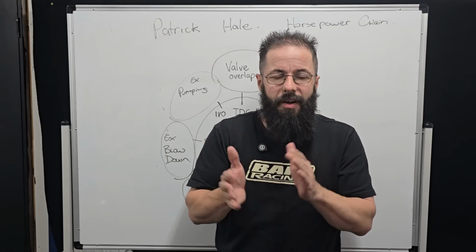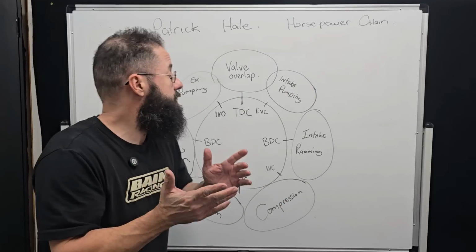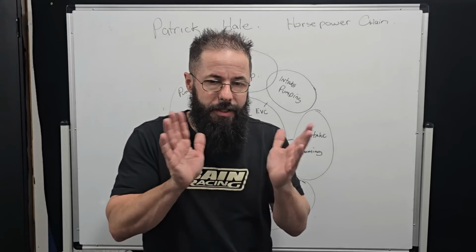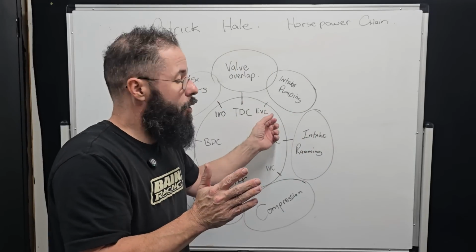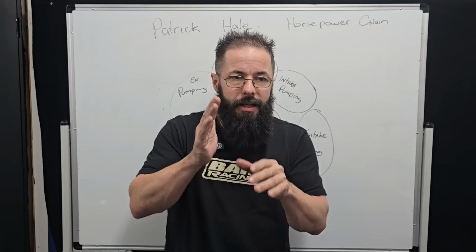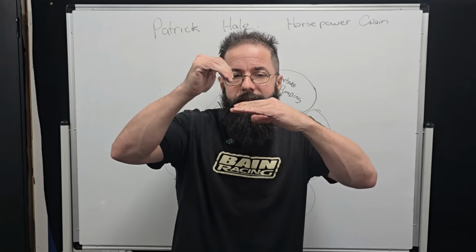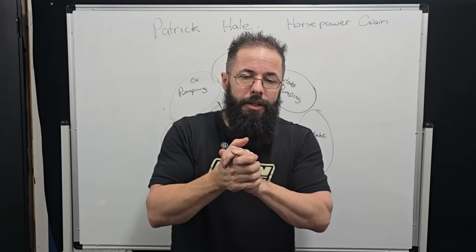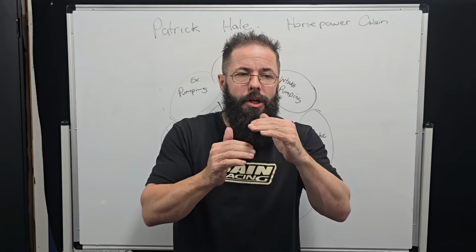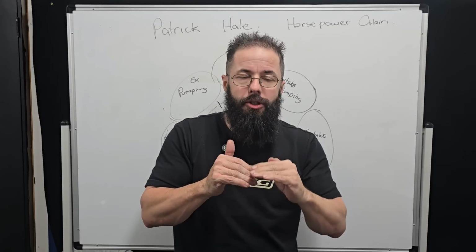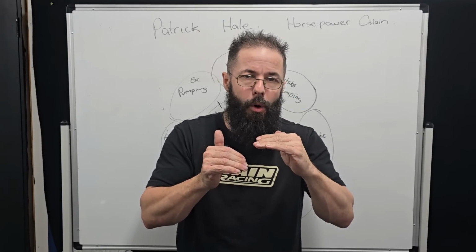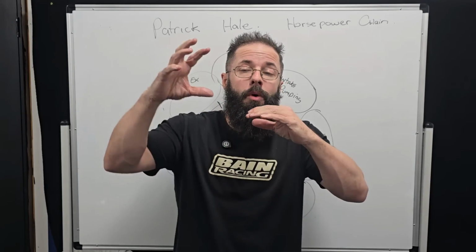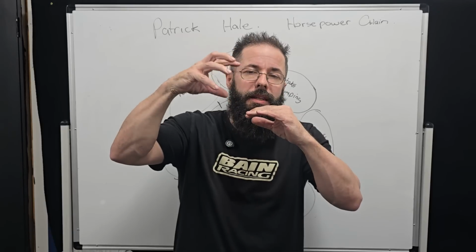Again, we'll break it up into different areas. Our most important part, I would say, would come down to our intake opening event. And again, this is going to be based off our exhaust closing event because that's going to set our LSA. But remember, we're opening the valve as the piston's coming up to TDC. And this is why wave tuning is so important, because we have no inertia, we have no piston drawing mechanism. So the piston hasn't gone down the bore at all yet to create the negative pressure needed for the atmosphere to fill it. So we're relying on a high pressure wave landing at the back of the valve.